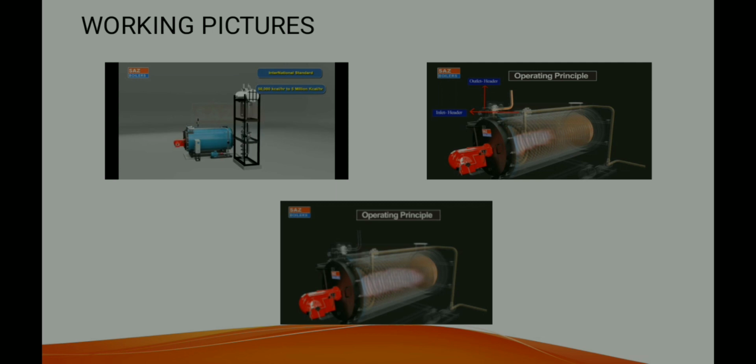the heater. Then the fluid is circulated through the pipe, and the burner starts running and creates heat by an indirect method, which is a convection heating method. And we have a temperature indicator, known as a temperature transmitter. The temperature is preset on the controller, and the fluid reaches its temperature and goes to the outlet heater nozzle in the thermal fluid heater.